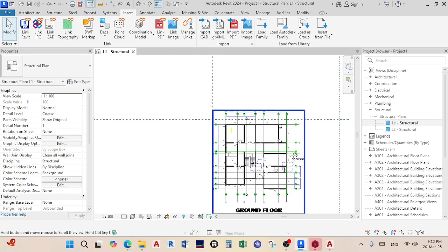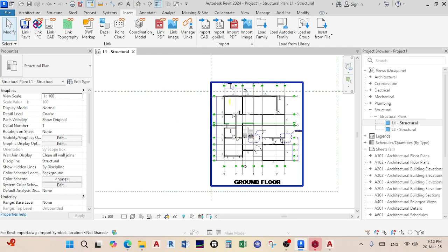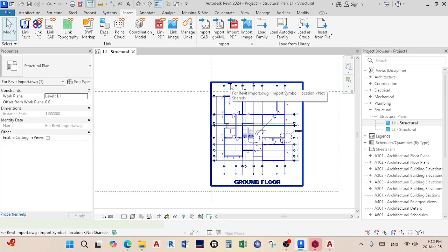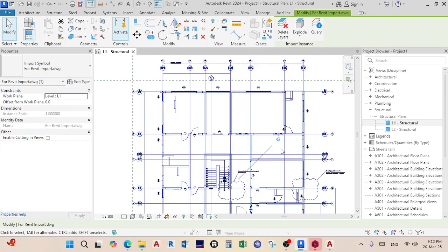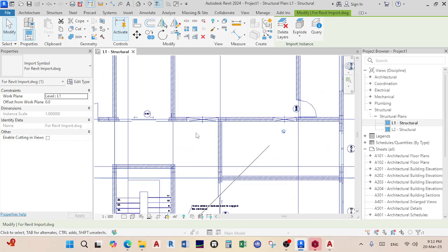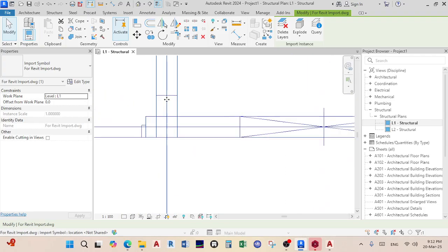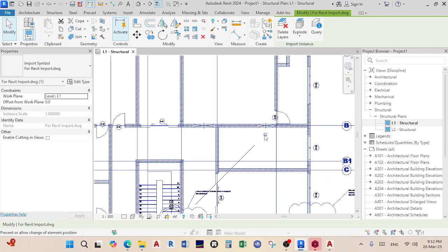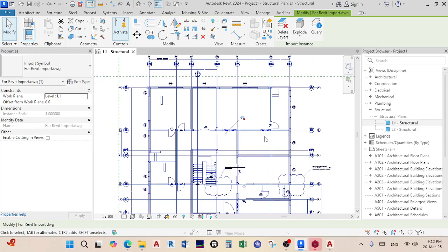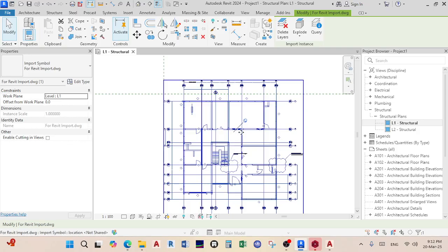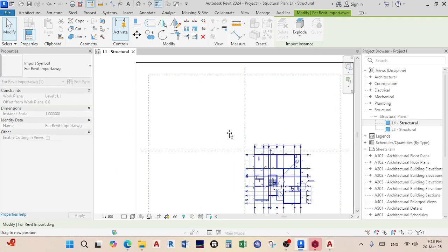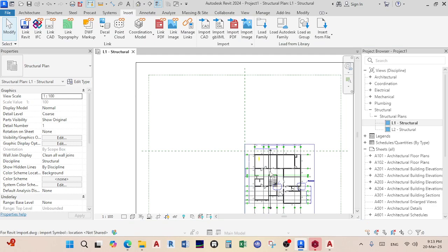When it comes into Revit, it comes as a pinned item, meaning it will be hard for you to make any changes to it. And my columns are there. You can either decide to unpin like that, or you can pin like that. When you unpin, it will be extremely messy. I would recommend that you leave it pinned. And the good part is that you can move.